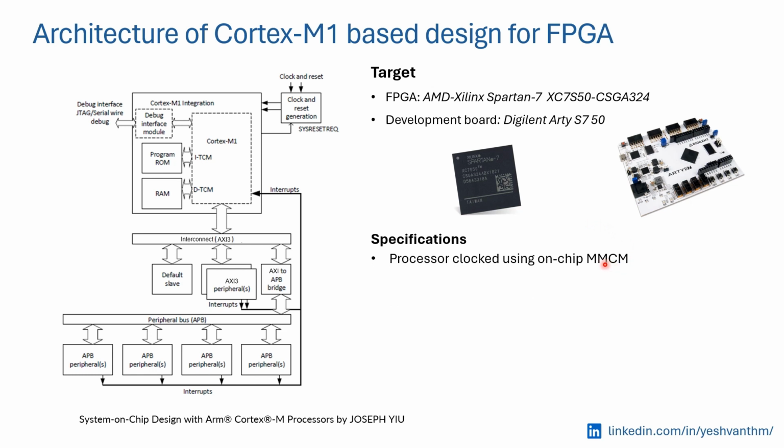We use a mixed mode clock manager for clocking the design, and then the processor system reset IP is used for the system and debug reset signals to the processor core. And the debug is taken out via the PMOD interface available on the FPGA board.